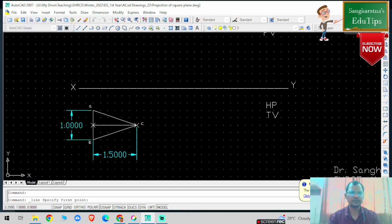I'm going to draw vertical projectors from this, select ortho here. From this particular point I'm going to draw vertical projectors. From this particular point I'm going to draw another vertical projector. Now you need to select the point here. So this is my first point, this is my second point.